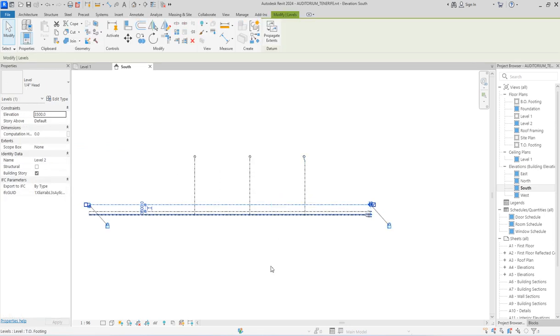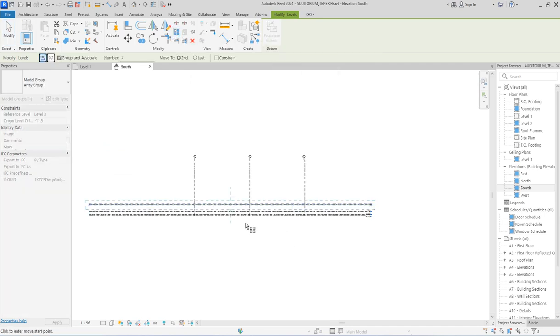So how will I do it? I click this one and go to create similar, or you click array. So this one will generate the array for you. What do you do here? You change this one to 18. We have 18 in number because we are going to 20. So we just type 18. So from this one to the last, you click here.